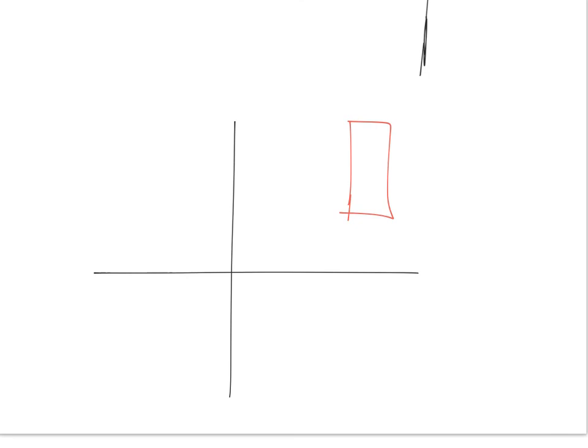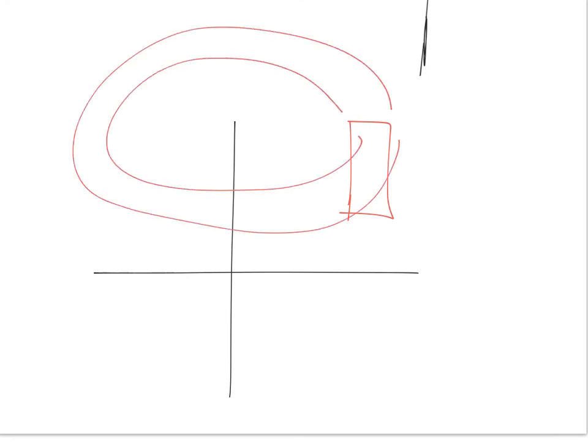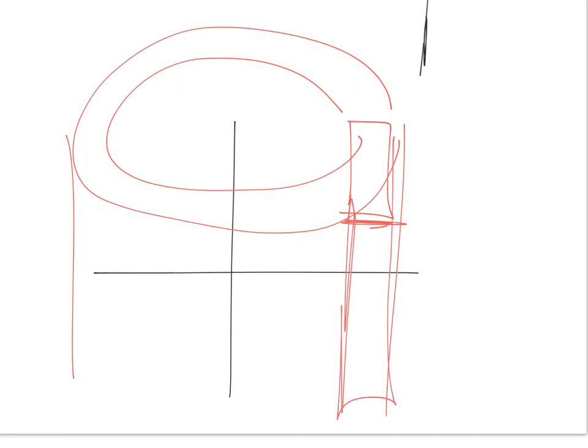In CAD work, you're going to do a ton of revolving and extruding. So you might have a rectangle, and you might extrude it to the third dimension, and then you get a prism. But if you take a rectangle and revolve it, you get a cylinder shell. So we're going to see a lot of this with CAD work. So it's important that we know that when we do something like this, we have to rotate it around, and we end up getting a cylindrical shape, however long this rectangle goes. Maybe it goes down to here. Okay? All right.